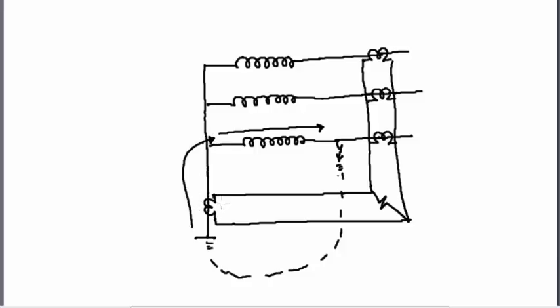So in order to balance this current, the current in the neutral should flow in this direction, and the current from the CT side, means from this side, will also be fed if there is a source on this side. Then in order to balance this current, the current should flow in this direction and take up this path, and at this node both these two currents get added up and the current will flow in this direction. It will take up this path.